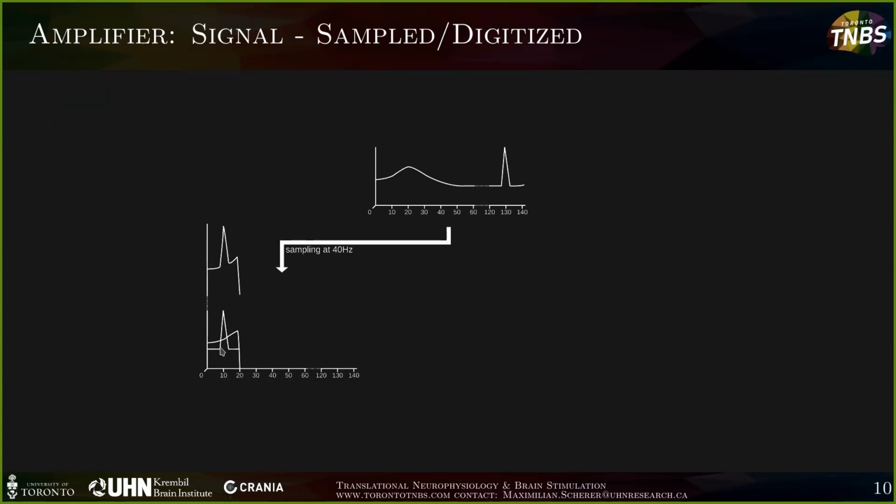And we're going to end up with this non-beauty here, which basically means we just cut into our 20 Hertz bin, which doesn't have a proper amplitude anymore. And our artifact here at 130 Hertz got wrapped around and around within this 20 Hertz block, which basically subtracts 20 Hertz from this 130 Hertz peak as many times until it stays within that bracket of 0 to 20, which, 130 minus 120, puts it at 10 Hertz.